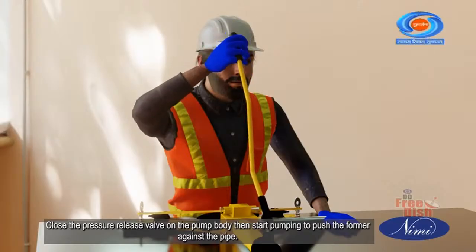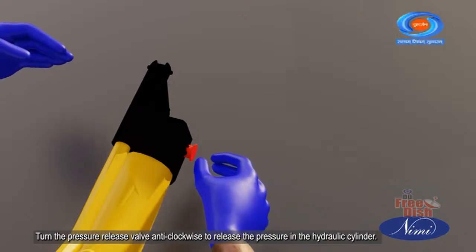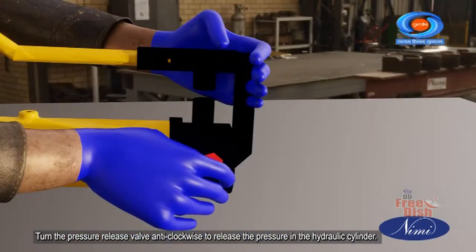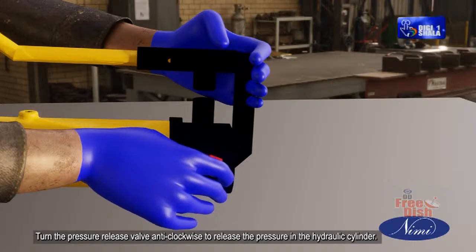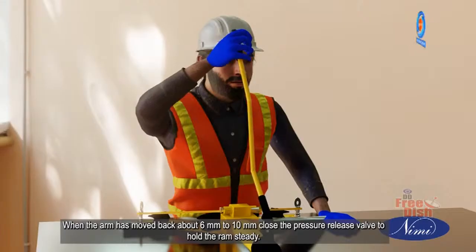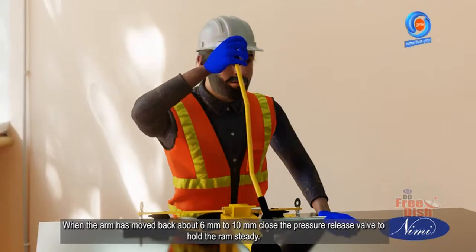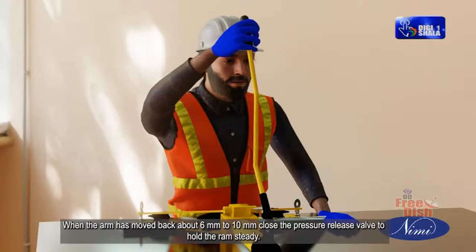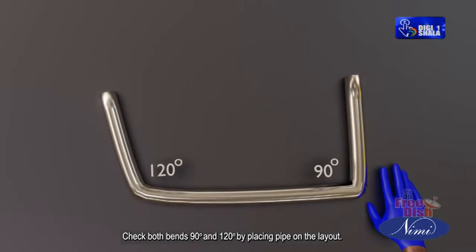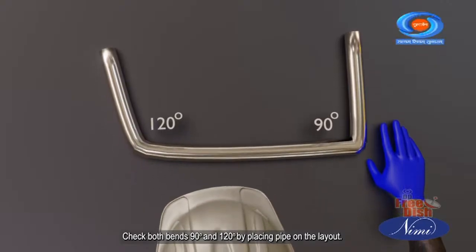Close the pressure release valve on the pump body, then start pumping to push the former against the pipe. Turn the pressure release valve anti-clockwise to release the pressure in the hydraulic cylinder. When the arm has moved back about 6 mm to 10 mm, close the pressure release valve to hold the ram steady. Check both bends, 90-degree and 120-degree, by placing the pipe on the layout.